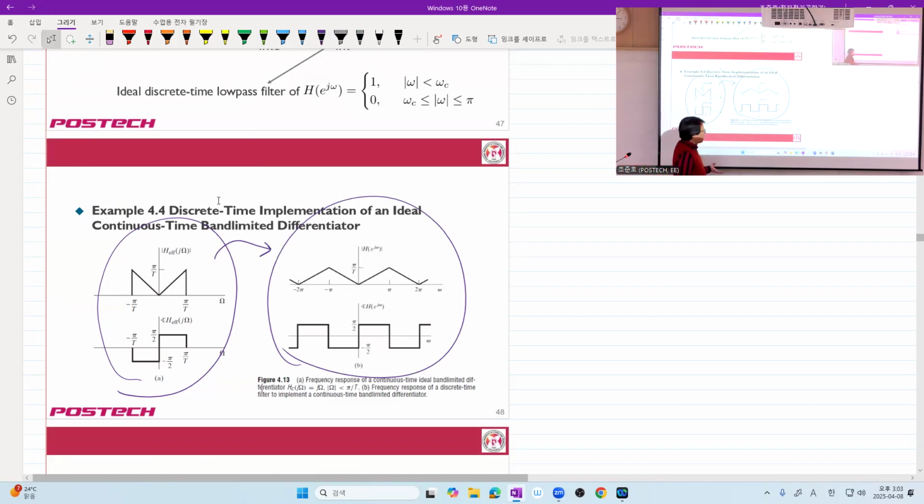And you may say, why? But differentiation is related to, in your basic circuit theory, the inductor if we want to generate it, right? So current in, and you differentiate, then voltage out, and that is the inductor, right? And an inductor cannot be easily implemented in 2 dimensions.